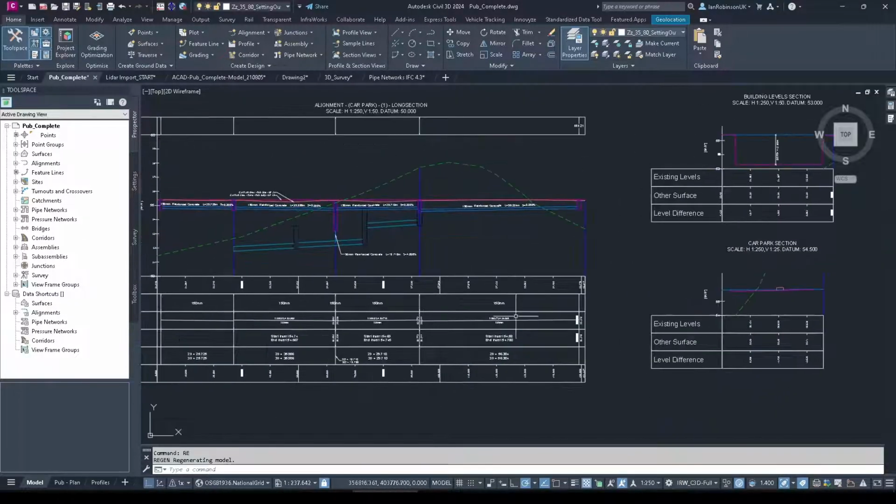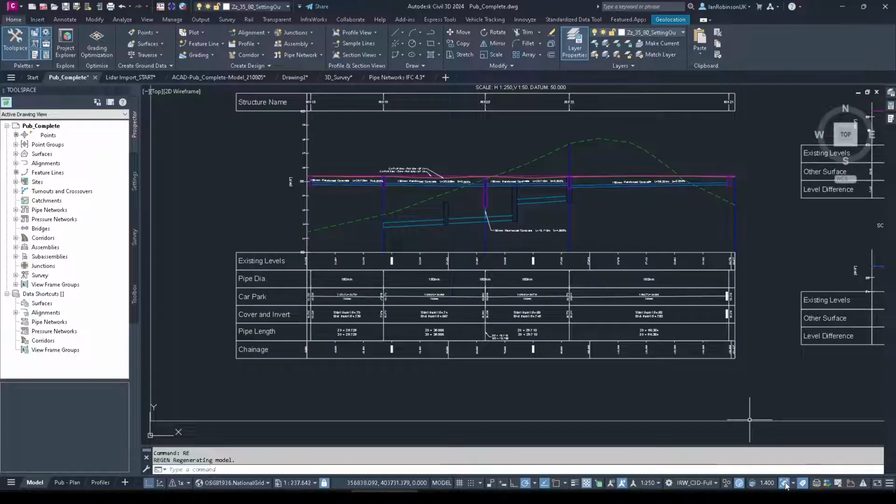So this is a new feature. It's turned on and off with this function down here, the AEC Label Optimize function. And you can turn these on for redrawing when zooming and panning. And you can change the level of detail for grouped labels, etc. And you can force a redraw of them.